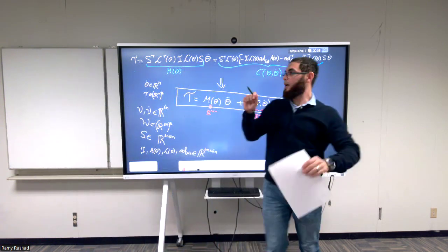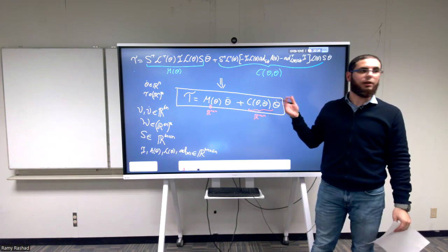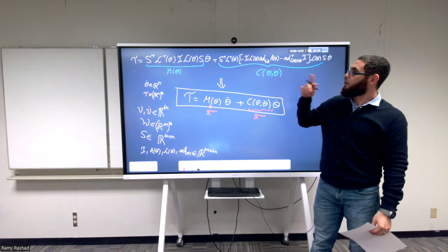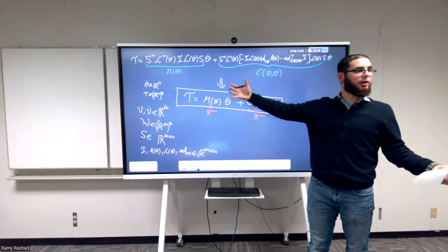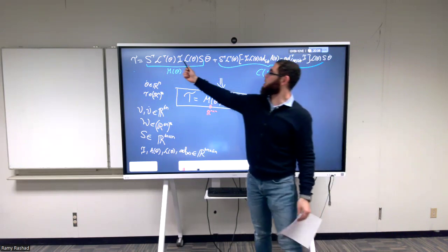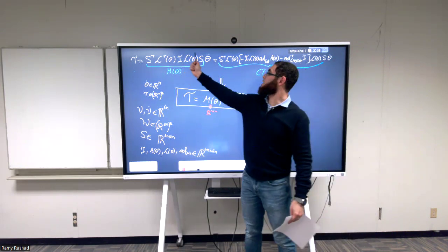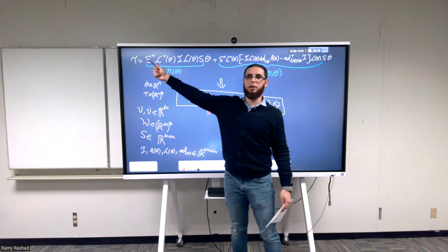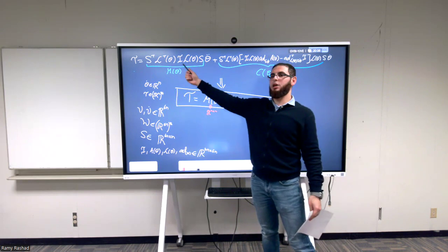One thing very powerful here, and you can see it clearly from this expression: even when we had something complicated, with many rigid bodies together, you see the inertia, this generalized inertia. How does it change coordinates? With some matrix, and it's transposed here. You remember what we said about the inertia?